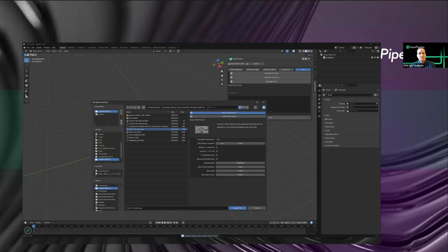But for CAD files, the first option that you have is basically how much resolution do I want to apply to the model. And by default, you'll probably find it's a good resolution, but you can choose different resolutions from these presets. And we also have a custom option, which basically uses these three parameters here.